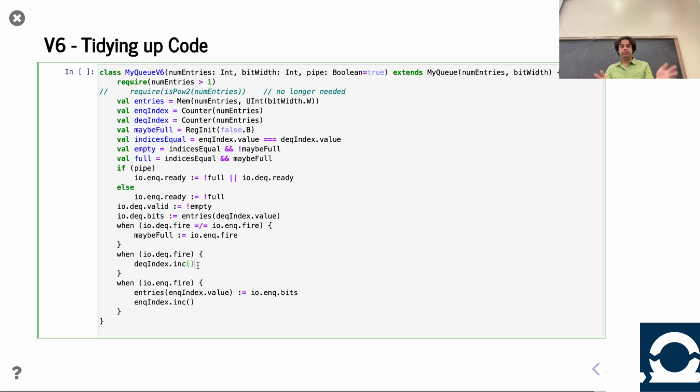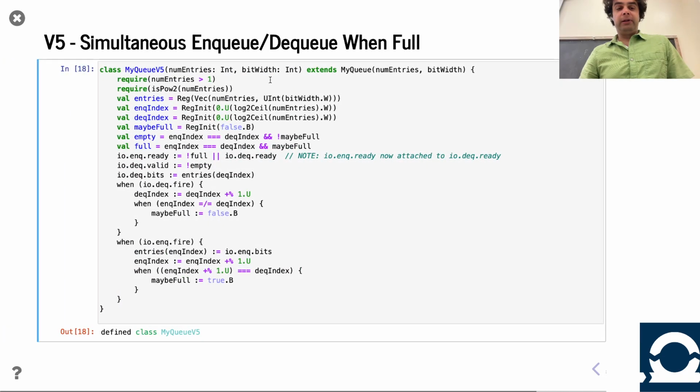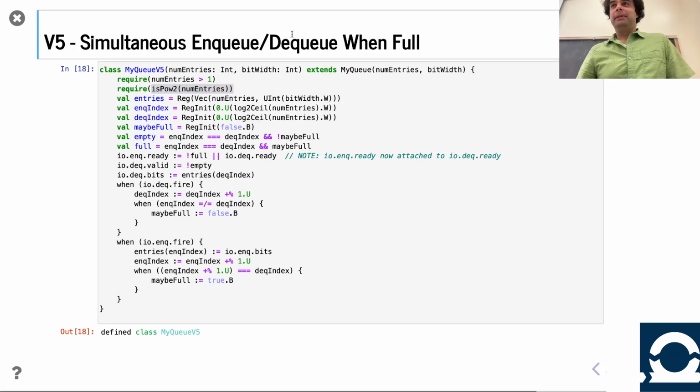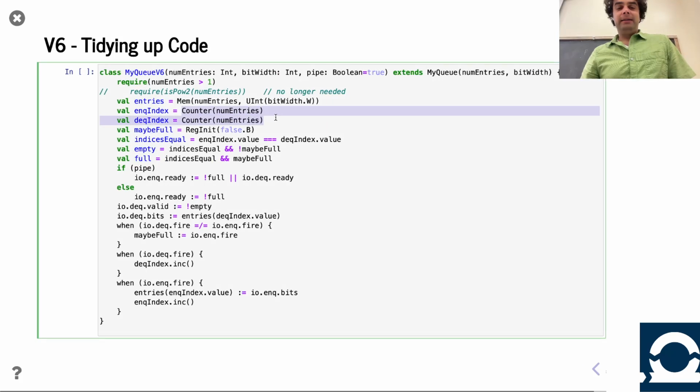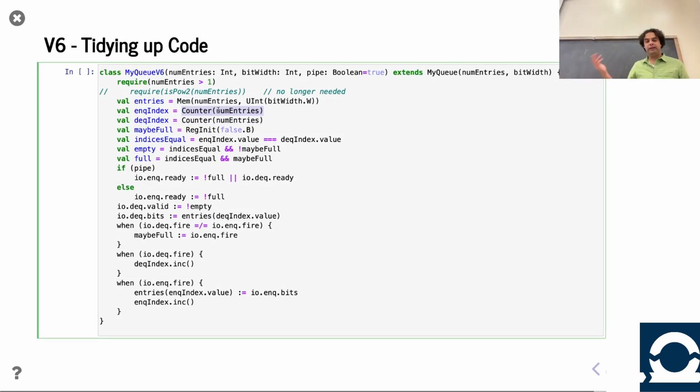And so, yeah, this is a better design. We are putting less complexity into our design by leveraging existing tested abstractions, and this counter abstraction makes sense. When I'm reading this, rather than having to figure out what's going on, like, oh wait, so and so declared a register, this value is zero, and has certain math about how big it is, and then I see them adding one to it, and oh wait, there's this detail of power of two too, that's how it does the wraparound. That's a lot of concepts to figure out when you're reading it. Versus using a counter. Hey, number of entries. Someone knows a counter is going to be increasing and then wrapping around. That all comes together, and you see a lot of this code gets simpler down here.